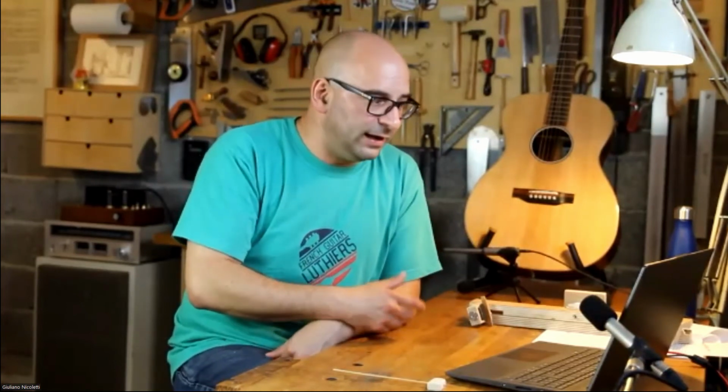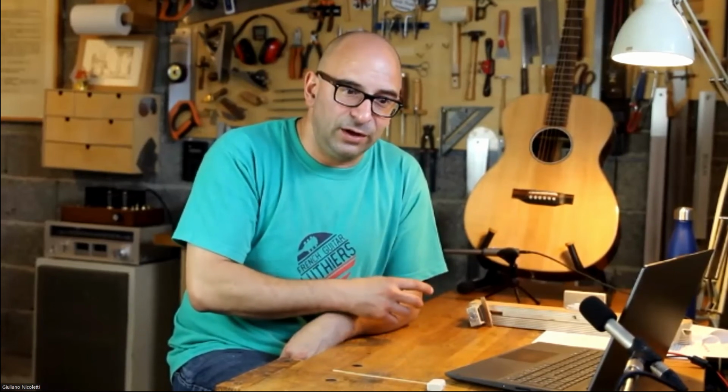So okay, in the end, the Taylor guitars that I had the chance to measure were not really exceptional, generally speaking, on monopole mobility measurements. But then again, when you cannot master the frequencies of the main modes, it is better to be a little bit on the heavier side than on the lighter side, at least since you work for vocal loudspeakers, yes.